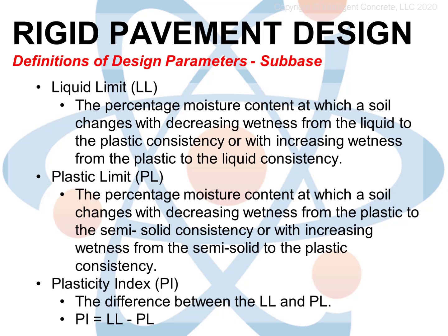Anyway, the plasticity index is simply the difference between the two moisture contents. A low PI, or plasticity index, of less than 10 or 15 means the soil will change fairly quickly from being stable, that is not plastic and not liquid, to completely unstable, that is liquid or mud, and not spend too much time, that is a narrow moisture range, of being in the relatively unstable plastic range, where deformations of the soil will readily occur.